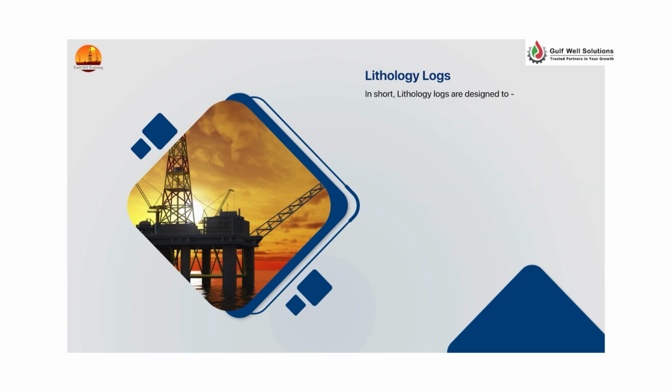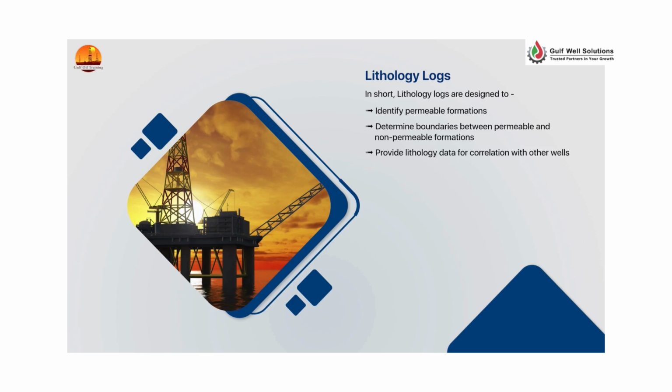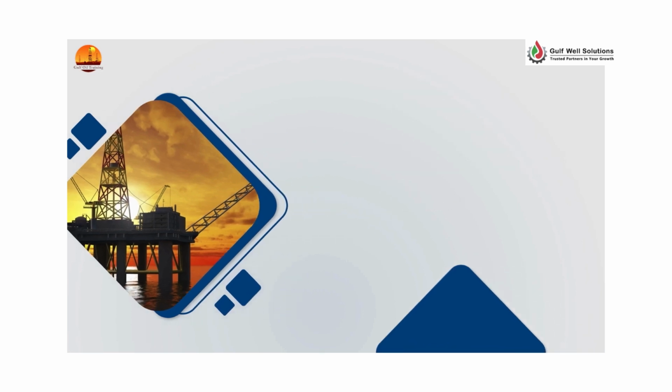In short, lithology logs are designed to identify permeable formations, determine boundaries between permeable and non-permeable formations, provide lithology data for correlation with other wells, provide a degree of certainty for quantifying the formation lithology. Examples are spontaneous potential and gamma ray.